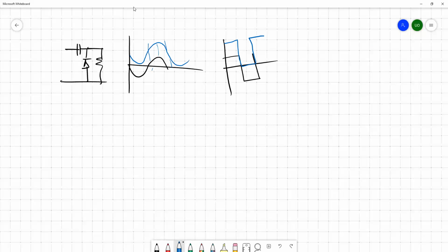During this transient period, your input and capacitor voltage may be different. Once this capacitor gets charged up to its maximum voltage, due to this time constant constraint, the voltage charged inside the capacitor never discharges or charges again through the load. So then the voltage remains as it is, and you can have a kind of a steady state response.